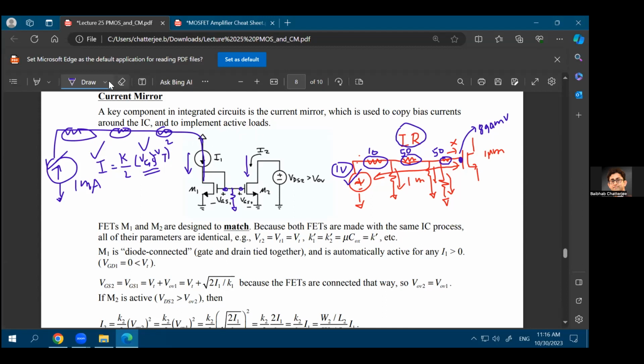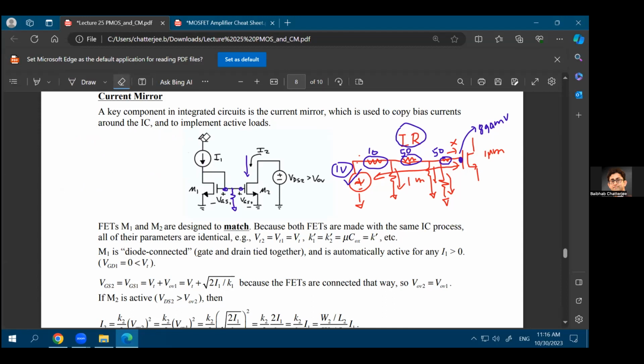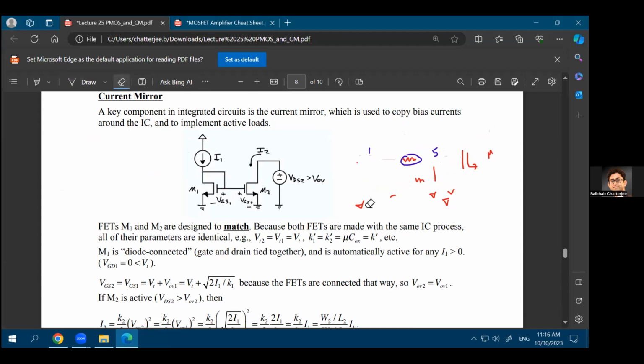All right. So now, assuming all of that is true, and we understand the motivation of why we want to use a current-based biasing, now we'll learn how you can use this circuit to create the biasing required for your transistors. Because eventually what you're trying to do is make both of these transistors in saturation. For example, let's say this is the transistor in your common source configuration. We haven't drawn it that way, but this could be one of the transistors in your common source configuration. And what you're trying to do is just create a correct biasing for this particular transistor.